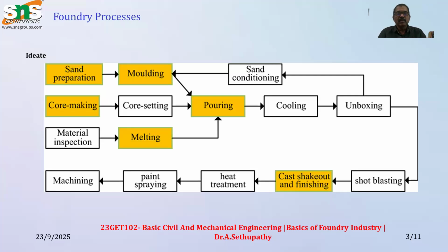The flow chart clearly establishes the foundry process and molding process. First is sand preparation to remove impurities, and making a mold through the pattern and molding boxes. Sand conditioning is mixing with some binding materials. Cores are important for making hollows or critical curvature areas.